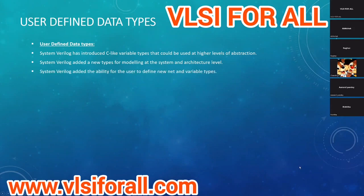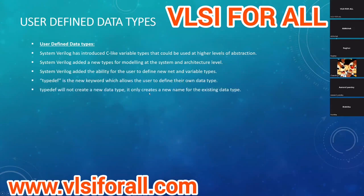So SystemVerilog can add new data types for modeling different system and architectural level designs. Let's say there's an FSM, and you can name the different states of the FSM, giving a name to each FSM state. You can model that using user-defined data types, and this adds the ability for the user to define new net and variable types. For this we use typedef.